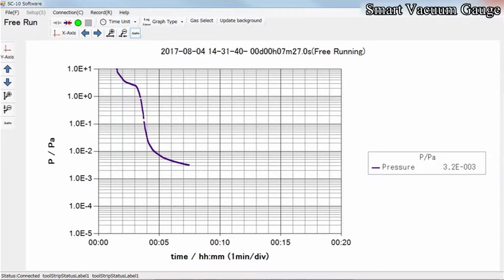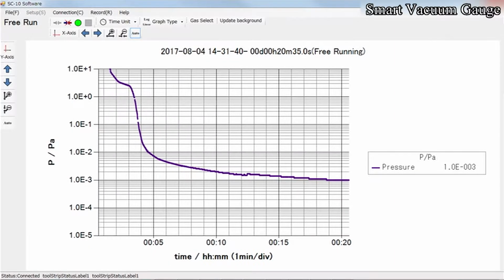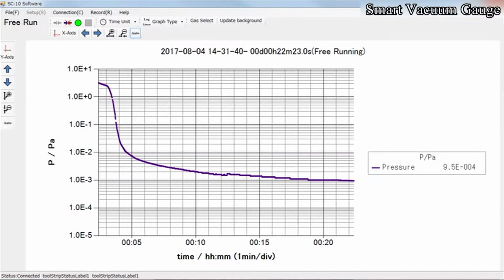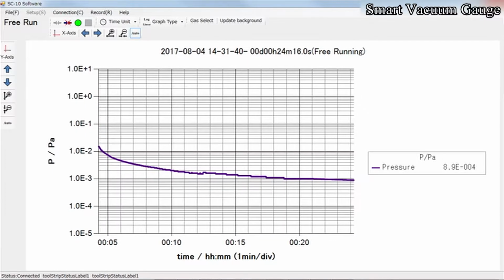Simply measuring the vacuum level, or rather the total pressure, with a vacuum gauge doesn't reveal what is occurring inside the vacuum when the condition of the vacuum system deteriorates, or when the pressure doesn't drop. Is the problem caused by gas emission, leakage, etc., and where is the leak coming from?